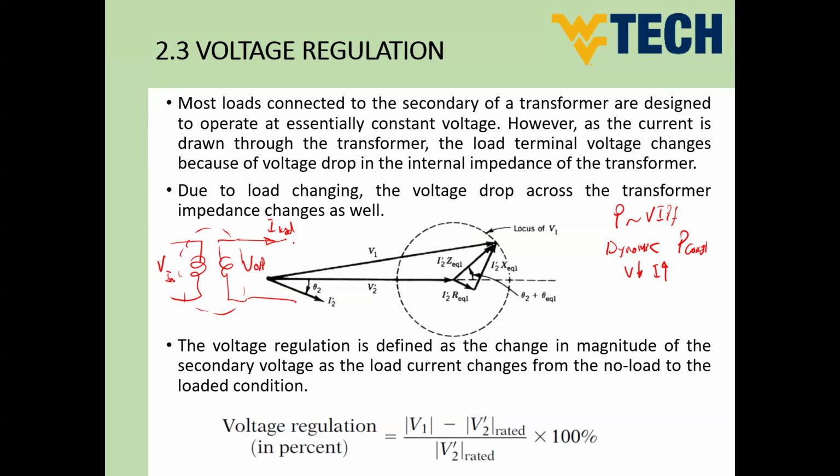I think we covered the power factor correction before, and you observe that if we inject reactive power in case of low power factor loads, this would reduce the overall absorbed current from the source. And this leads also to reduce the volt regulation across our transformer. And this also will make our output volt constant enough to keep our loads safe and avoid any abnormal conditions. So this is the concept of why it's important to know the voltage regulation of a transformer.